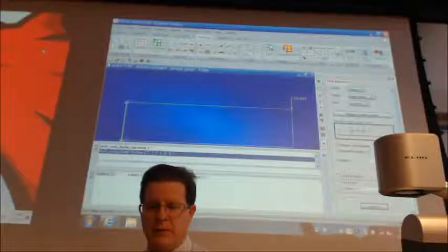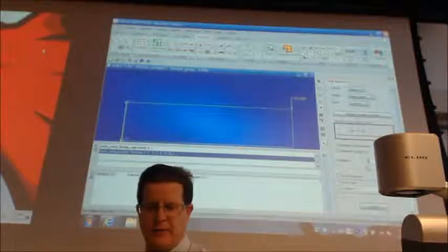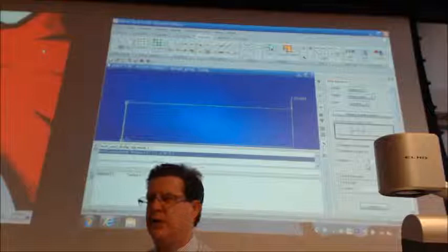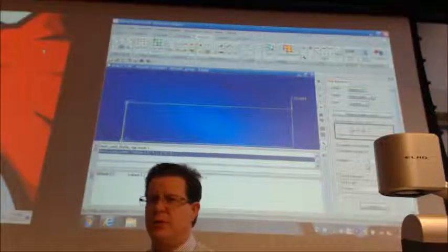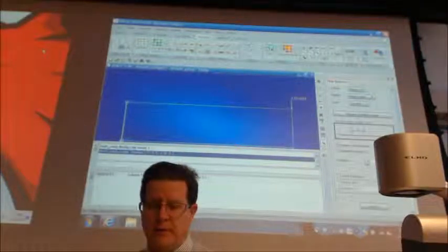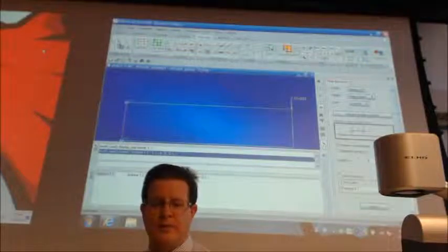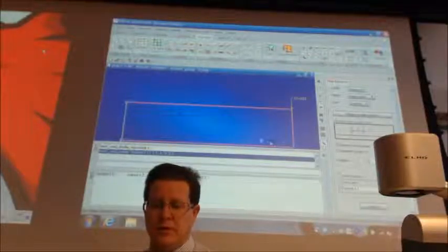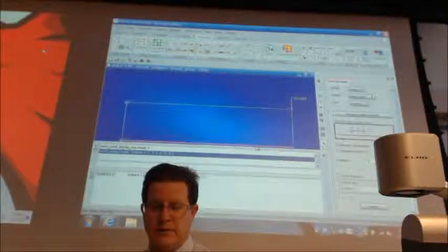And then we want to change it to 5. We could change it to any number. It could be 10, it could be 2, it could be 100, whatever we want. But remember, we're doing mesh seeds here. So I'm going to select this surface, which is 1.4.